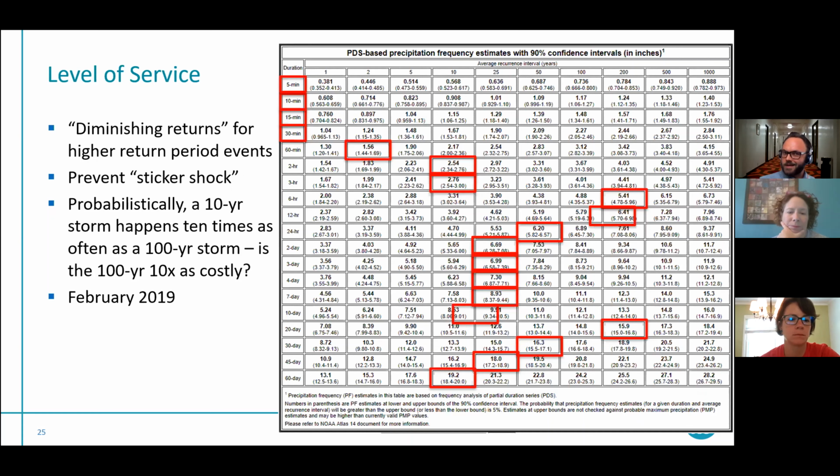But if you model the 10-year storm, and the same things are inundated, but they're 1 foot deep in the 10-year and 3 feet deep in the 100-year, you're not getting the right criteria for benefit cost out of that. And choosing the right return period of event that's somewhere in that Goldilocks zone will help prevent the sticker shock of the solutions as well, because trying to corral a 100-year storm is honestly pretty inadvisable and unrealistic. But if you can find out that in some areas you're going to get 100-year storm benefits with a 10-year storm improvement, that's nice to know as well.